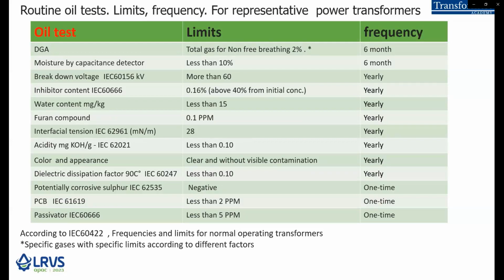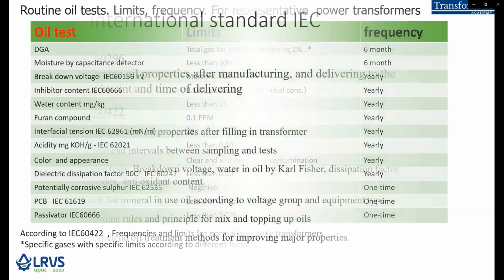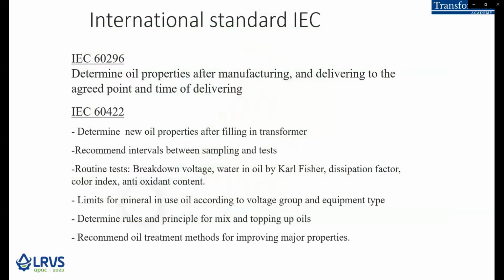This is a table of the routine oil tests according to IEC standard, with the limits and test frequencies. Both limits and frequencies should be adapted to the transformer specification. Here are the relevant IEC standards for tests and limit values for new oil and service oil. Of course, there are different values for different equipment types.